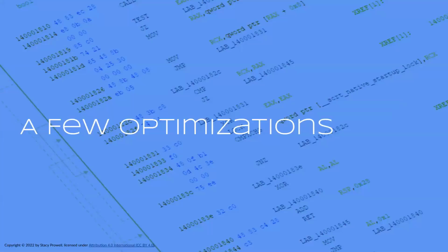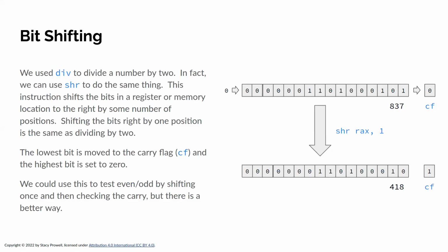So there are some optimizations we can make in the program, and bitwise operations are great. The processor can do these really, really fast. It has specialized hardware called barrel shifters that can make these kind of operations nearly instantaneous. And so the div instruction is a really good instruction to take a look at because it's both complicated and obscure, and it's also very, very slow comparatively.